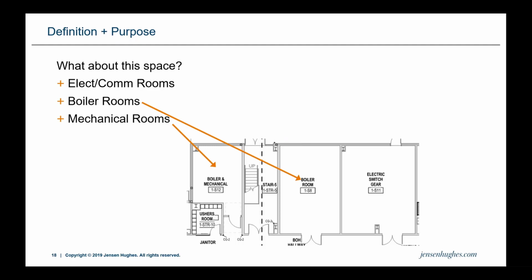What if that boiler room or the mechanical room has an ambient noise level of 90 dB, for instance? Well, that would mean our speakers need to produce 105 dB. We're getting very, very close to the upper end of where we should be. So we've got to be careful when we take a look at some of these spaces.